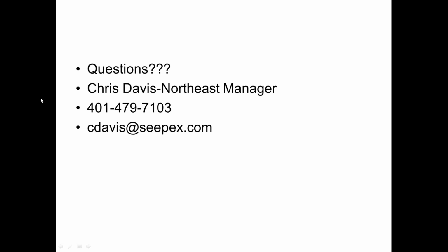The question is, what is the maximum temperature allowed for the progressive cavity pump? That would be depending on the elastomer choice. Most of the progressive cavity pump elastomers would limit us to about 350 degrees Fahrenheit. Although if we went to a metal to metal option with low discharge pressure, you could probably go to higher temperatures than that.